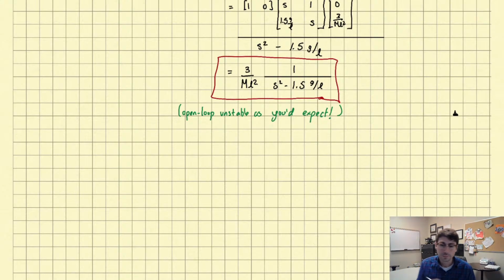Okay, so let's step back to think about what we've done so far. You have a nonlinear system because the physics are naturally nonlinear, or life is complicated, so things will typically tend to be nonlinear. We put it into state space form. That's the first thing we did. Then we learned how to linearize it to get a linear state space model. And now we just learned how to take that state space model and generate a transfer function.